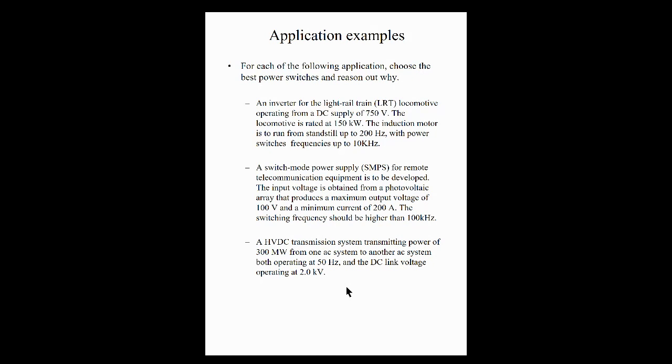So I think number 3, the thyristor can work because it's a low frequency, high power application. Yes, you can use thyristors there. That's correct. All right. How about the second scenario?